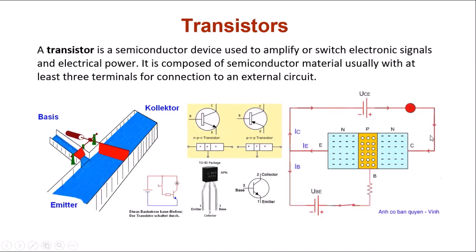Here also, if you'll see, these are two N type semiconductors, so there won't be any positive or negative terminal side. So emitter, because here emitter is connected to negative, so here also emitter will be connected to negative, and the other terminal will be connected to positive terminal of the battery. So to operate the transistor, this circuit arrangement we need to make in terms of common base, common emitter, or common collector connection.